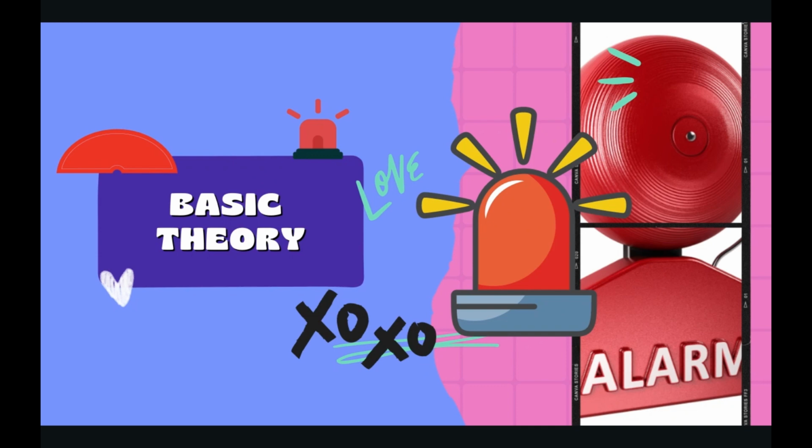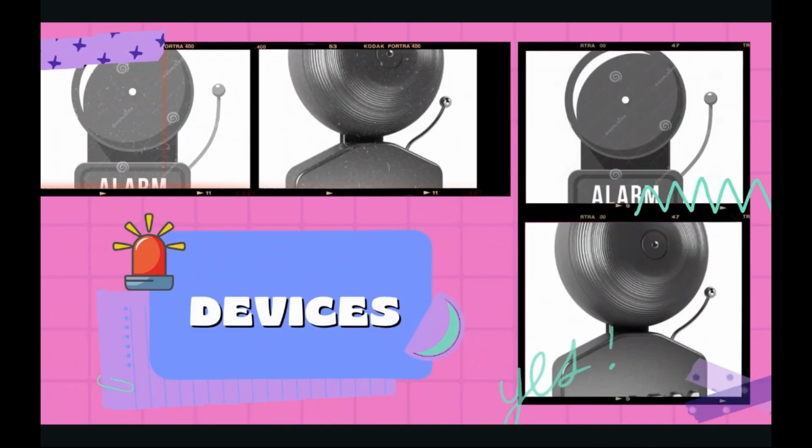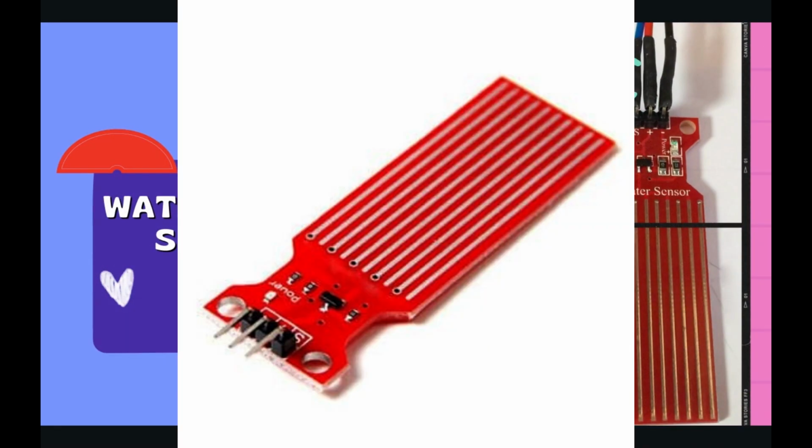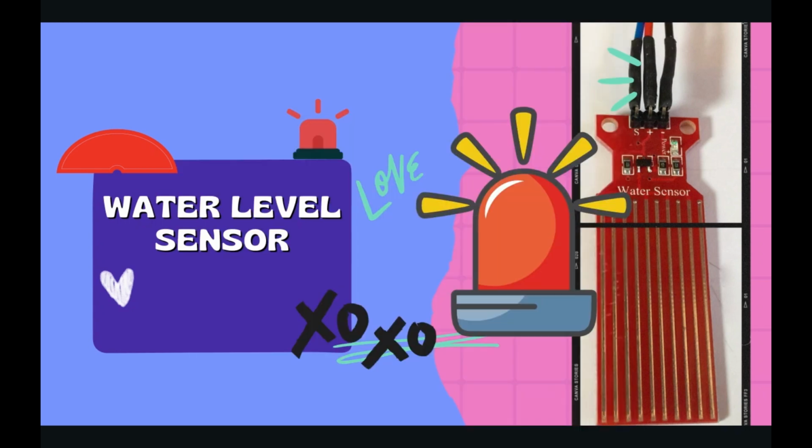And here are the devices for the disaster alarm, namely the water level sensor. This water level sensor is a type of analog sensor with an operating voltage of 5 volt DC. This sensor has dimensions of 60 mm x 20 mm x 8 mm with a detection area of 30 mm x 16 mm, a sufficient size for prototype scale.